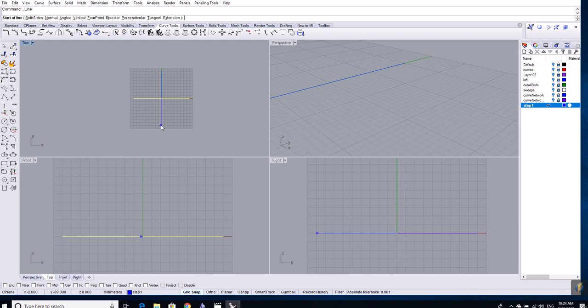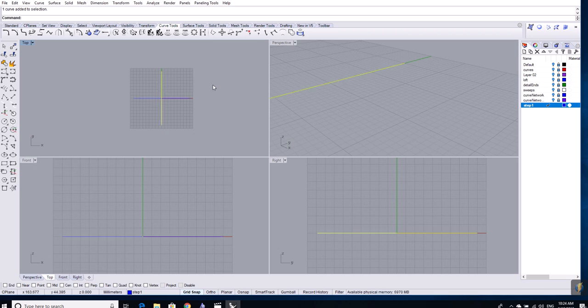This is a technique we're going to be using quite a bit, construction lines, because they give you something to snap to. And if we're mirroring our shape or line shape, we know that the endpoints of the lines are going to connect exactly at the same point, and then we can make closed surfaces out of that.